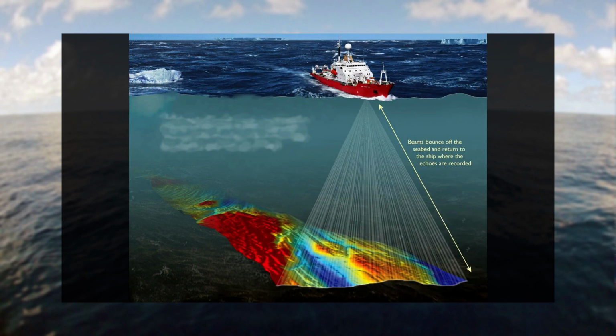By simultaneously collecting a dense grid of depth soundings, MBES systems resolve not only bathymetry but also seafloor backscatter intensity, which correlates with substrate composition. The resultant data sets provide a comprehensive and detailed representation of seabed morphology, enabling the identification of fine-scale features, quantitative geomorphological analysis, and the creation of realistic shaded visualization. This represents a paradigm shift from one-dimensional depth profiling to true high-resolution mappable seafloor characterization.